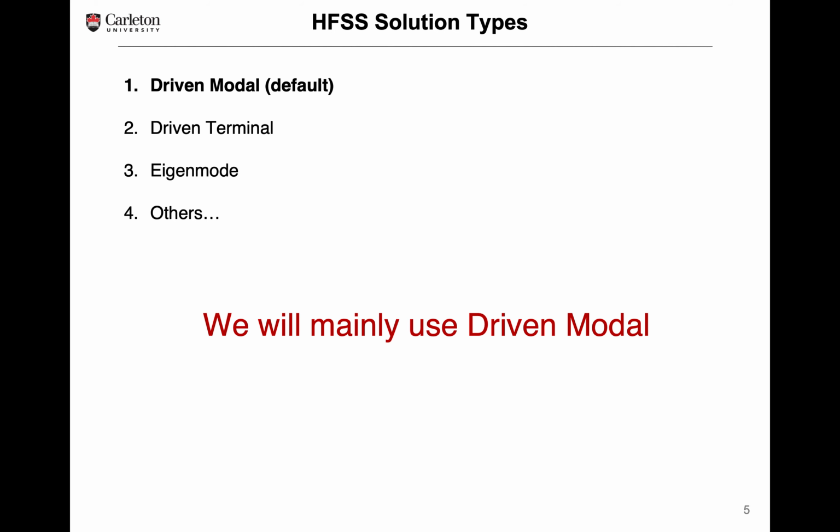So for the solution types, there are a number of them, and I'll let you guys read on that later on, but the one that we're going to use in this course is the default solution type, and it's called driven modal. You don't need to know the differences between them, but for example, with driven modal, you have to set an excitation in HFSS, but the eigenmode would calculate the modes inside a structure without you having to set an excitation. But in any case, the default mode is a driven mode, and that's the one that we're going to use throughout the course.